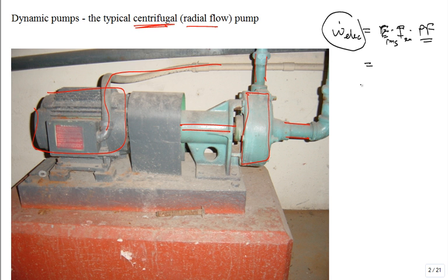Well, only a fraction of that gets converted into the shaft power, true? And so that's our efficiency of the motor. So the shaft power, then not all of that mechanical power is converted into the fluid power, just a fraction associated with the efficiency of the pump.